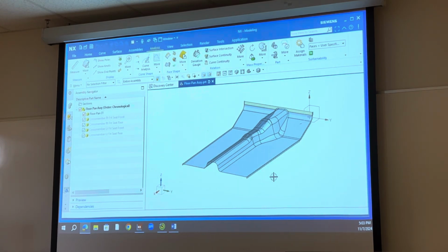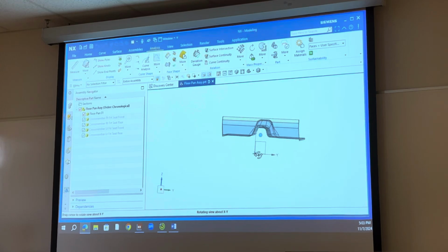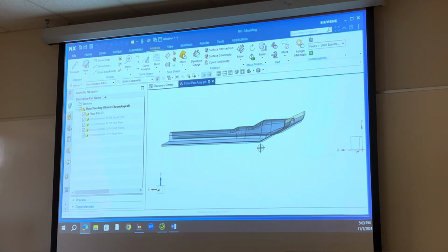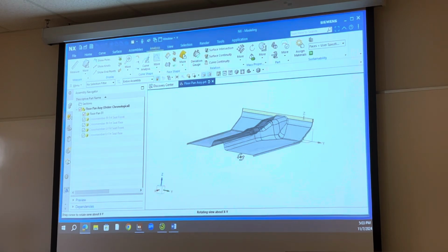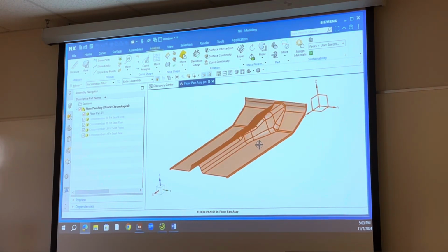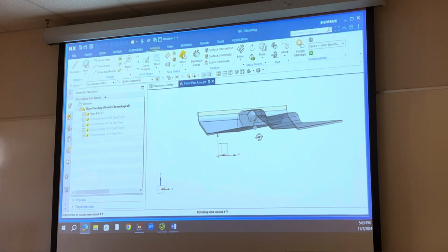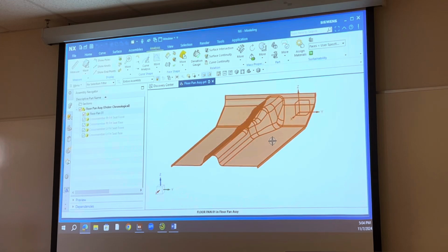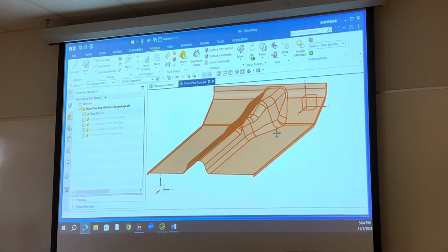So in this case, there's a converter, like a catalytic converter, and it's sitting under the part over here, kind of towards the front like this. And there's requirements that it can only be a certain distance because of the heat and everything. It can only be a certain distance from the metal of the floor pan. And where they tell us this converter is, it's too close to the floor pan. So we have to make a little clearance area. It could be done a few different ways. The way we do it is to kind of put a little bump in the floor pan right here. And underneath that bump is where that converter is, and making it rise up here in the bump, that makes it a valid distance from the converter, so the heat is not going to be an issue, right?